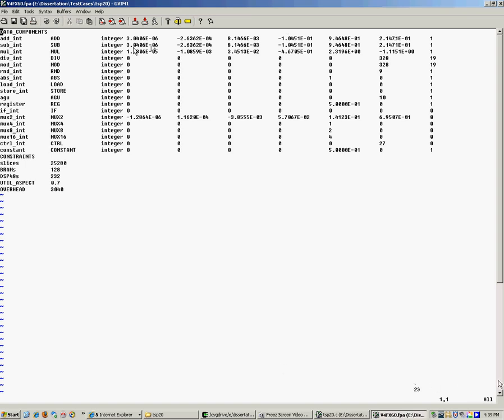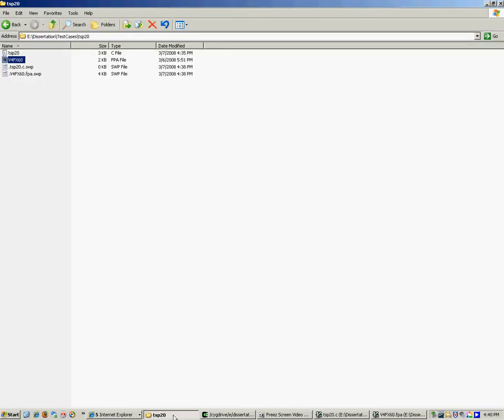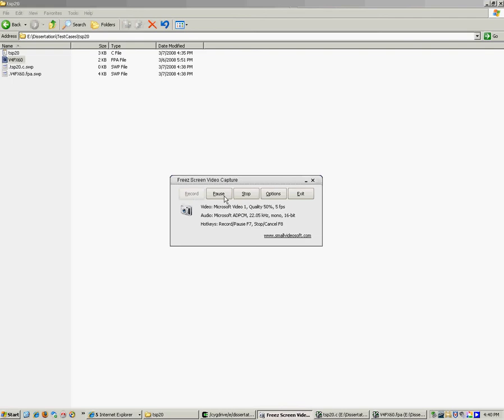Also, for each of these components, the performance can be characterized by a fifth order polynomial that describes its resource utilization. So these columns are the coefficients for those fifth order polynomials. And this last column over here is the latency of each of the items. That describes the only two input files that you need for your system.